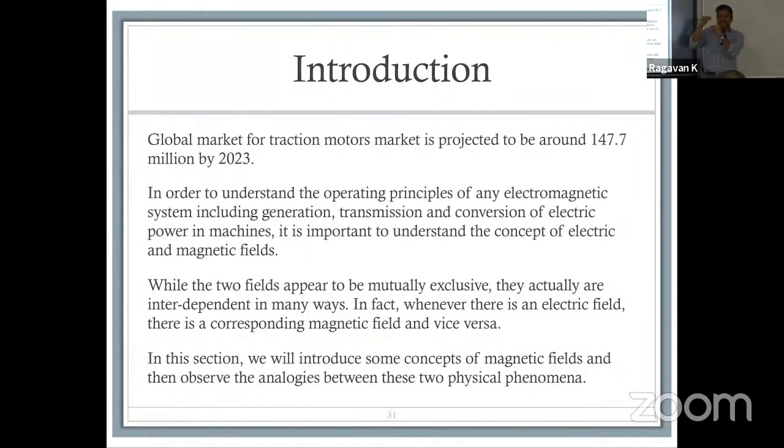So at the same time, if you start to separate them out, you give it a little bit of space between the housing and the stator back iron. Arguably, you could get a lot less acoustic noise because there's a spacing. Problem is, you'll also have lower heat transfer coefficients, right? So the heat transfers in a similar medium to sound, which means you might end up having to optimize or select which one is more important, or how you are going to optimize within your tolerances.